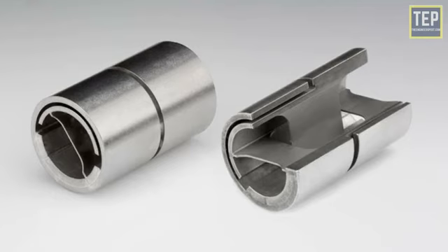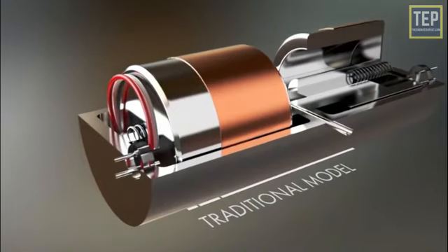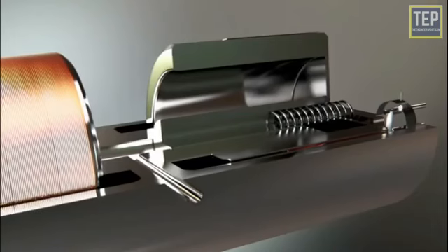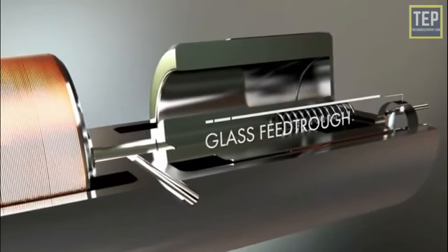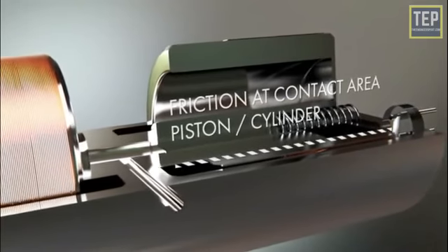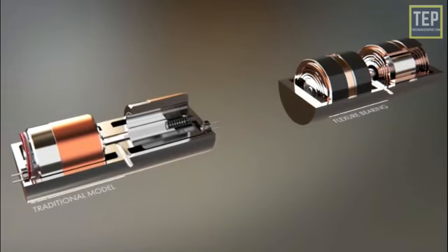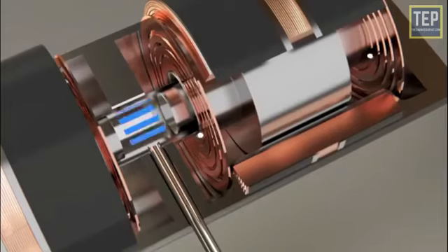A flexure bearing is a category of flexure which is engineered to be compliant in one or more angular degrees of freedom. Flexure bearings are often part of compliant mechanisms. They serve much of the same function as conventional bearings or hinges in applications which require angular compliance. However, flexures require no lubrication and exhibit very low friction.